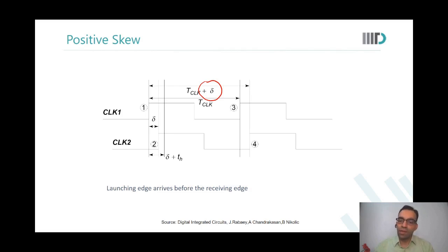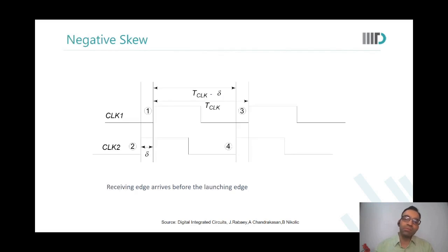And if it was a negative edge, you will actually have lesser time for your combinational logic. But sir, I will be less worried about the hold time now in the negative. Yes, you will be less worried about the hold time. So we'll just see.